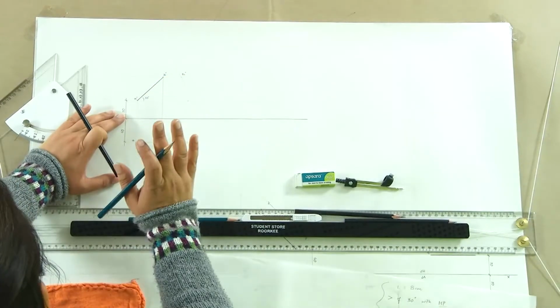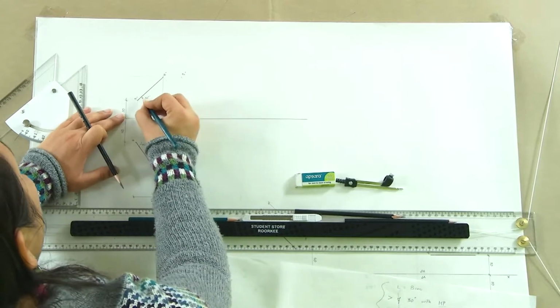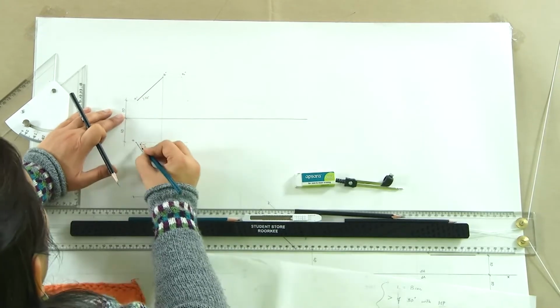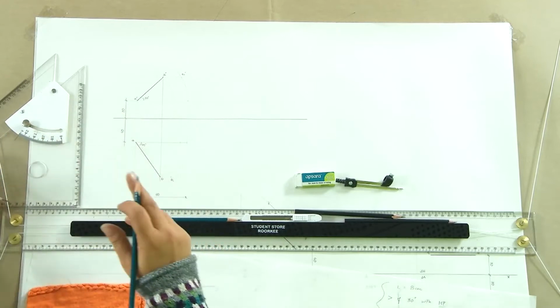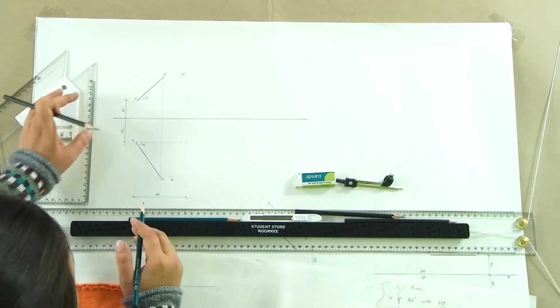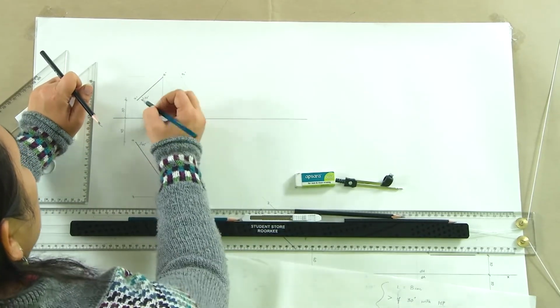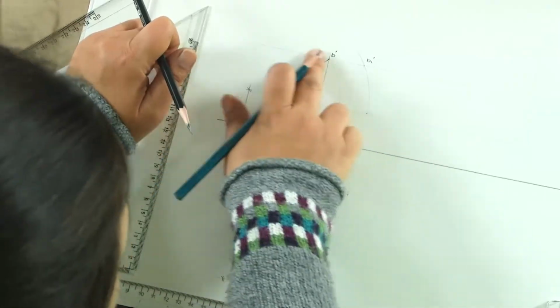In that case, we might be given the horizontal trace and the vertical trace of the line which is inclined at certain angles, and in addition to that, we might be given the angles that the projections make. In that case, the same process will be done, but in a reverse manner. So, what we would do here is, we will draw the traces at the given angles, say alpha and beta, and then draw the locus of it.